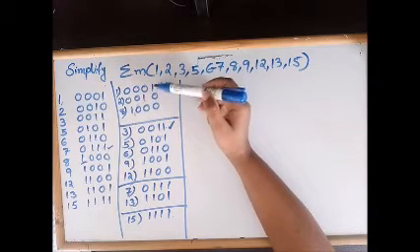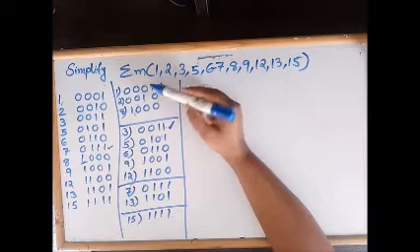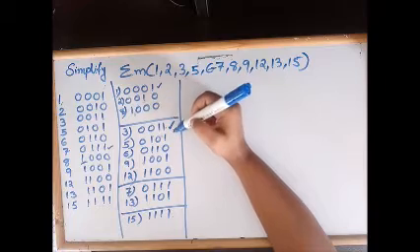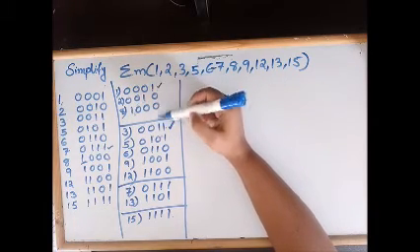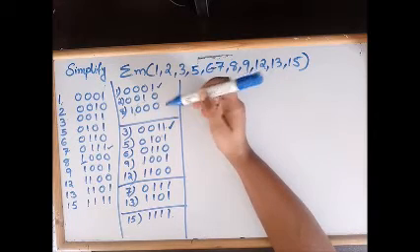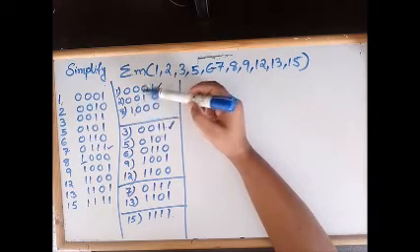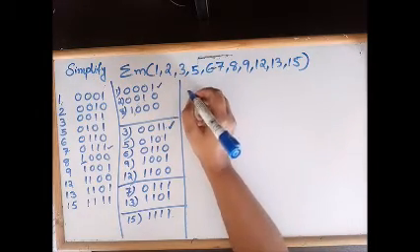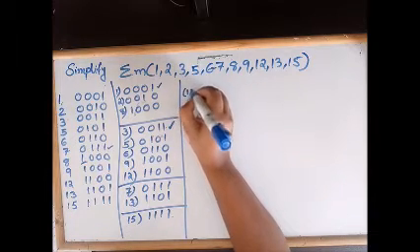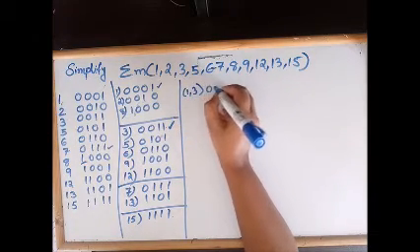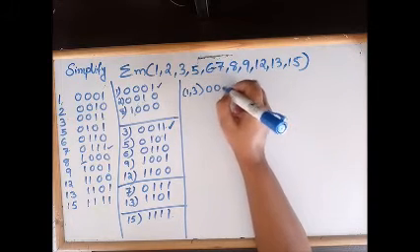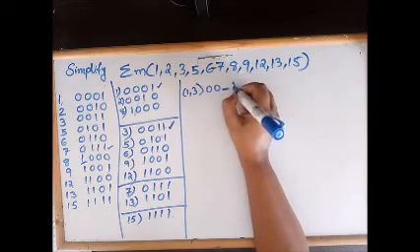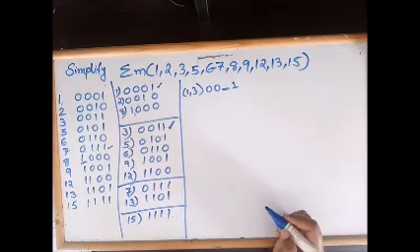So if there is only a single bit change between the terms in two succeeding groups, then we can combine them together by placing a dash symbol on the mismatched position. That means in this case, first two bits are same, only this third bit differs. So we can combine these two, that is I can combine 1 and 3, and when you combine, the same things are the first two bits and difference is for the third bit. So I put a dash here and again the last bit same, so I can write it like this.